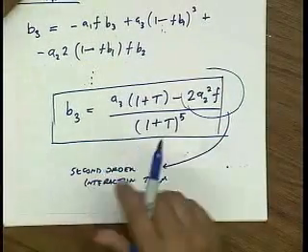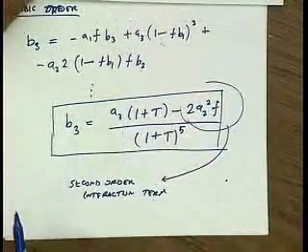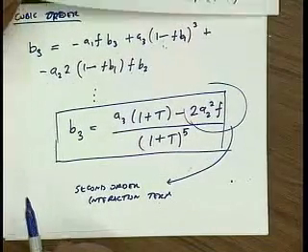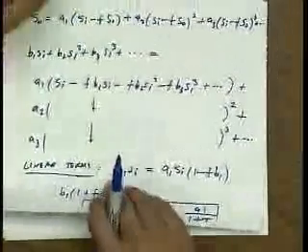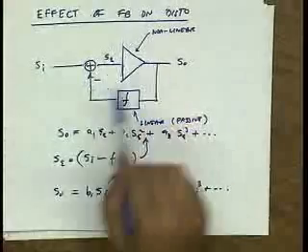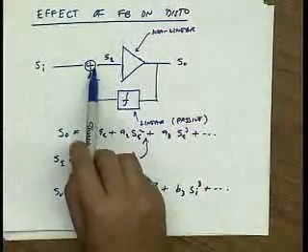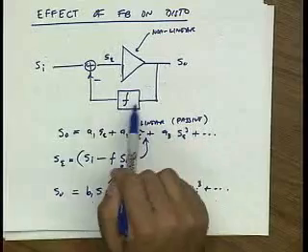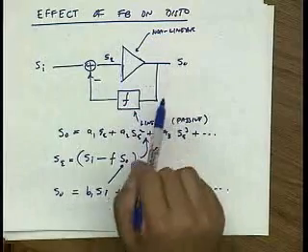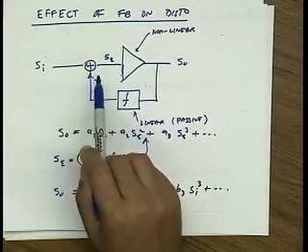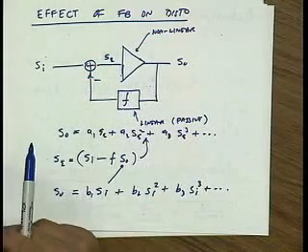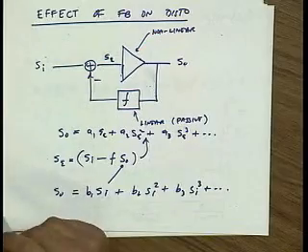Okay? So where does this cubic distortion come from? Anybody? How do we get cubic from second order in a feedback system? Anybody want to venture a guess? Let's look back at our system. Let's say that this only has second order distortion in it. Well, input signal comes in, I have second order distortion, it gets fed back, right? It gets summed with my signal and it goes through again. And so the second order interacts with the first order, and through that square nonlinearity generates cubic distortion. Okay, so that's why we call it second order interaction.